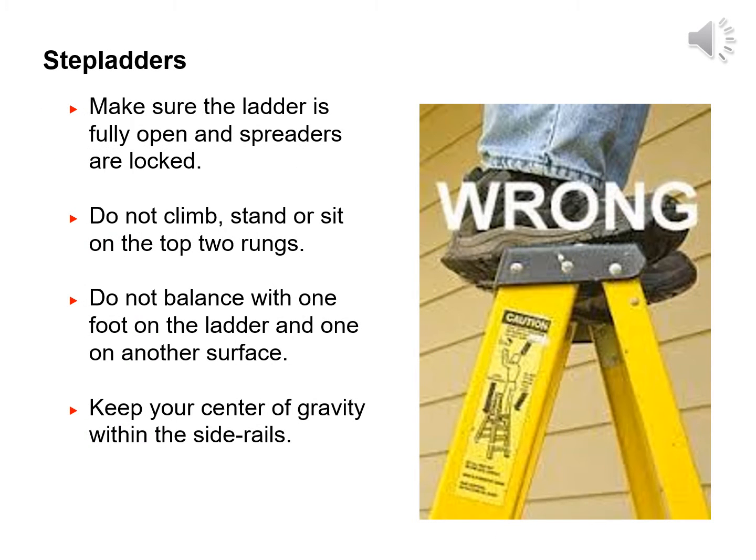To safely use a step ladder, you must make sure the ladder is fully open and that the spreaders are locked. You should never climb, stand or sit on the top two rungs. Also, do not balance with one foot on the ladder and one on another surface. This increases your chance of becoming unbalanced and getting seriously injured.